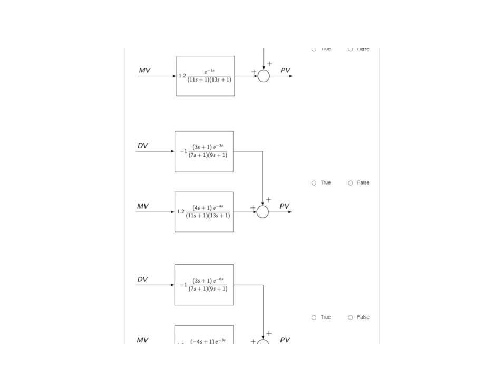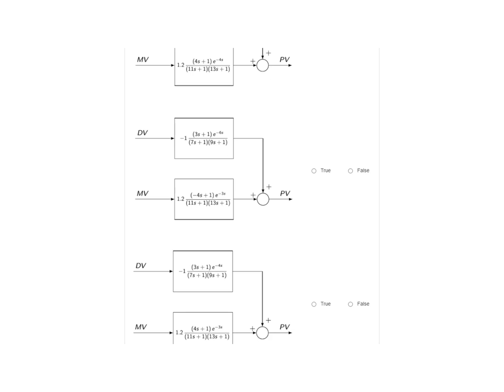Well, in this third example we have a problem with the delays, right? The delay in the process is larger than the delay in the disturbance dynamics, so in this case the ideal feed forward cannot be implemented. It is not realizable.